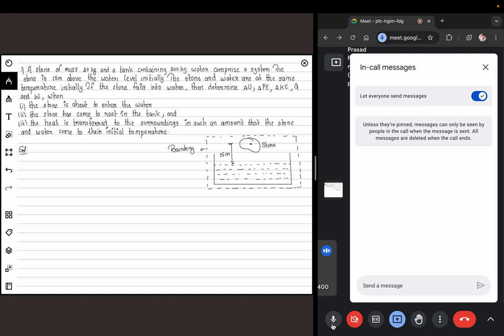How do we solve such problems? The first step in any of these problems is to start with your first law. So what does the first law tell us? The net heat transfer across the boundary, and this is my boundary, is the net change in energy plus the work done by the system, where this delta E is composed of several quantities like delta U plus the change in kinetic energy and potential energy, that is, the change in internal, kinetic and potential energies.